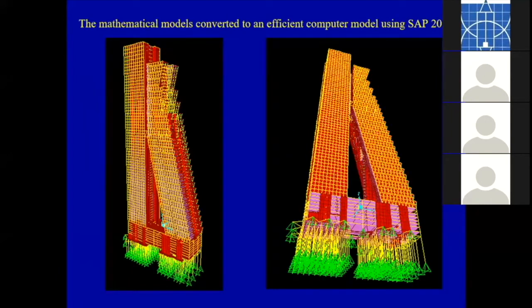And you can see this model of Altair that I made in 2012 or 2013. I made these models in 2012. And you can see in the model you get the superstructure above the transfer plate. Here you get a transfer plate, then the superstructure below the transfer plate, and then the foundation, the piles all modelled, and a certain stiffness has been allocated to represent the bedrock stiffness.